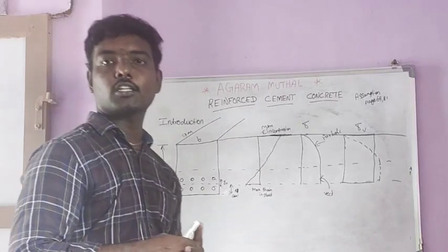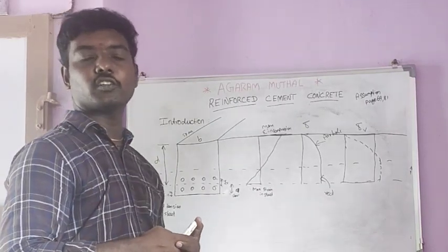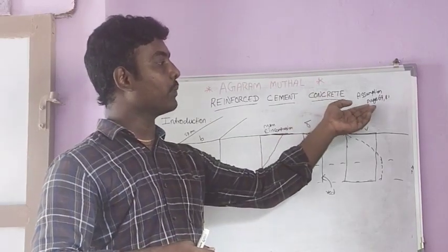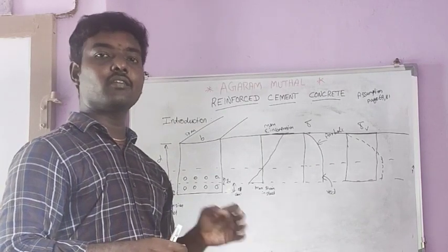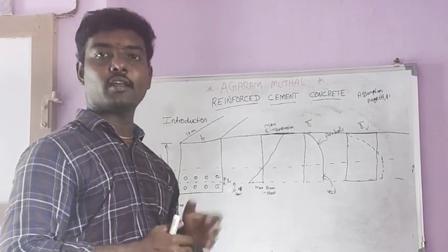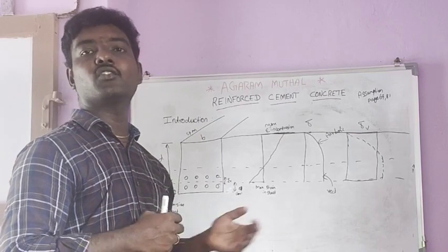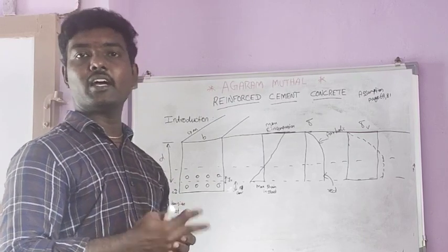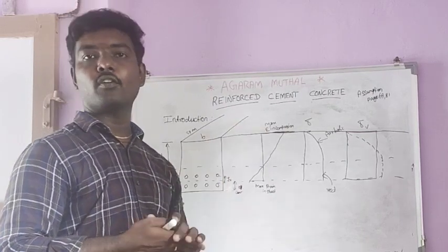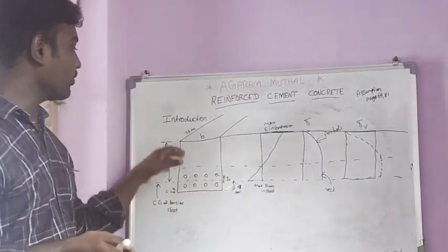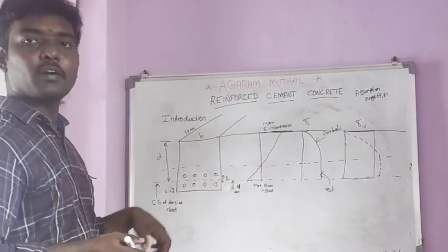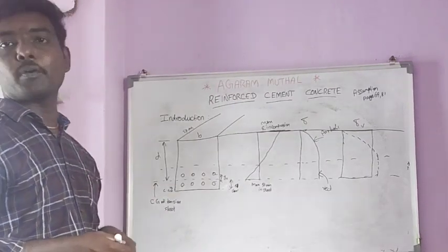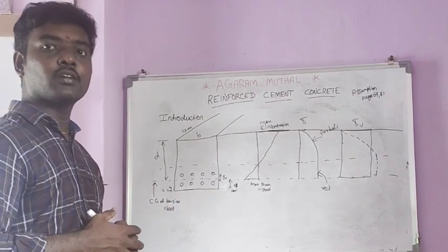Okay. So some of the assumptions followed for RCC structures are given in IS 456 at page numbers 69 and 81. Some of the significant assumptions are that the plane section remains plane after bending, and the strain and stress variations are linear throughout the span. These two are the main assumptions in IS 456 2000. Based on that, if you are taking one beam, the depth of the beam is capital D. So we are giving each of the components which were discussed for design.